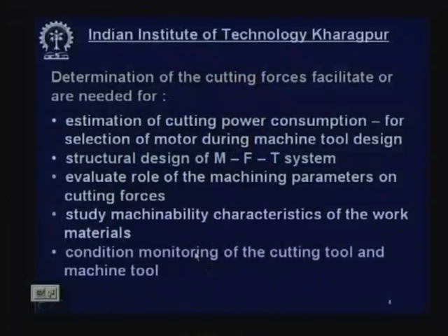But how do you know that the tool has worn out? We cannot take it out from time to time, stopping the production. So, we have to continuously monitor or measure the cutting force. From the change in the magnitude and pattern of the cutting force, one can understand the condition of the cutting tool or even the machine tool. If the machine tool is defective or has some problem, then the cutting force pattern will change. So, we should continuously measure or look into the variation in the cutting force magnitude and pattern, static or dynamic. For these reasons and purposes, the cutting forces have to be known offline and online always.